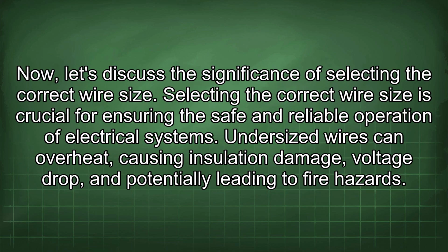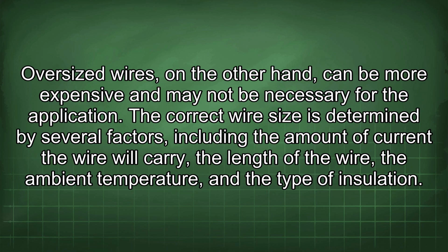Now let's discuss the significance of selecting the correct wire size. Selecting the correct wire size is crucial for ensuring the safe and reliable operation of electrical systems. Undersized wires can overheat, causing insulation damage, voltage drop, and potentially leading to fire hazards. Oversized wires, on the other hand, can be more expensive and may not be necessary for the application.